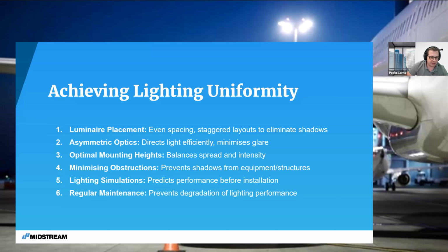Another thing which is very linked to this same aspect is the optimal mounting height. The higher, the better, always, is a rule when trying to light something uniformly. So a ratio between the size of the area and the height of our lighting point assures to be able to reach the furthest point in the area without having to either increase too much the tilt or increase too much the light in the part closer to the light source.